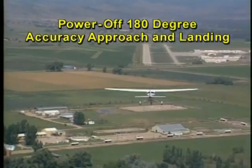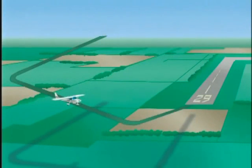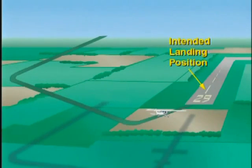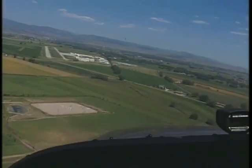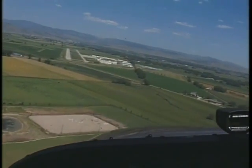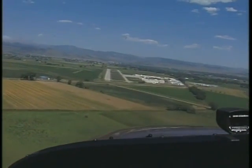Let's look at another maneuver, the power-off 180-degree accuracy approach and landing. It's an approach to land with the engine at idle that uses only the glide angle under prevailing wind conditions to fly a specific pattern and land on the runway at a predetermined point. Power-off accuracy approaches and landings are designed to develop your ability to judge gliding distance and to control descent angle during a power-off approach to a safe landing.